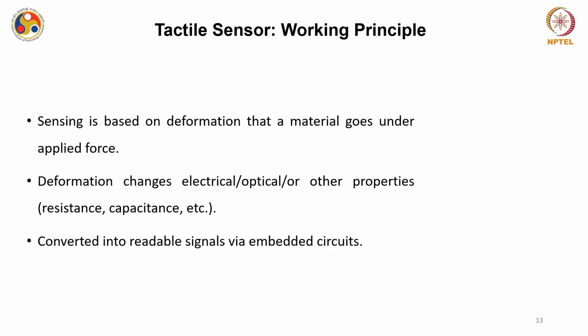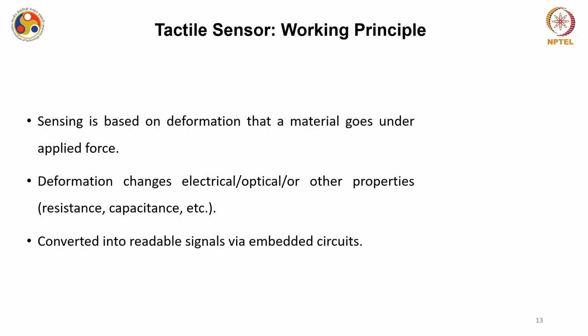Please note that the working principle of all these force sensors or tactile sensors is based on the deformation that a material goes through under the applied force or applied pressure. Deformation changes the electrical property or optical property, or sometimes the magnetic property. We'll see some of them. Accordingly it can be converted into a readable signal via the embedded circuit on the same board.